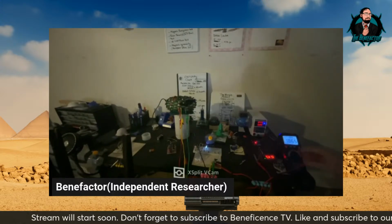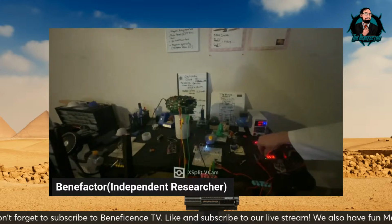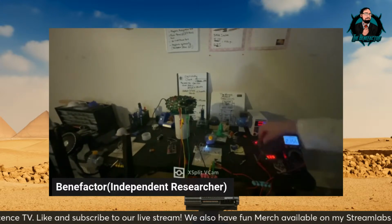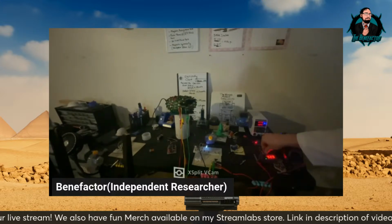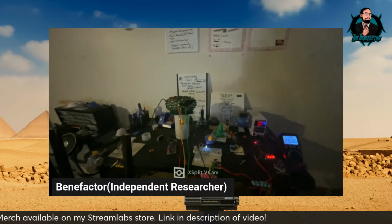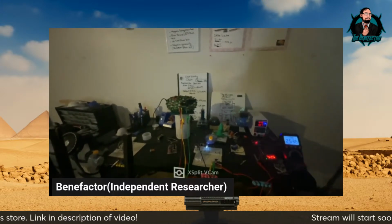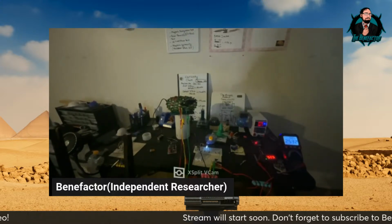Let's see. So we have it at 19% high duty cycle, 1% low. We're slowly increasing the high. And as we increase it closer to 50, it is outputting more volts. But the amps are increasing as well. So I'm trying to find the sweet spot, the most efficient spot, right?